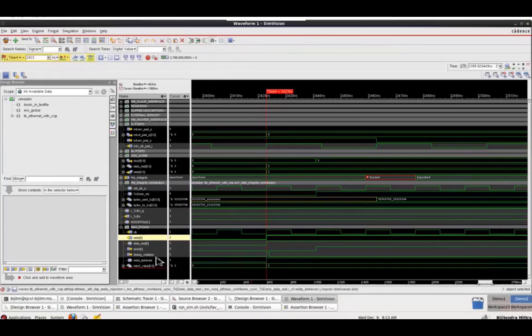So this is the injection witness I talked about. It says that there has been a timing violation and it is of hold type. So that's why the output of the flop happens in the same cycle. As a result, the TX done is going high one cycle early, which is messing up the comparison. That is why it is failing.